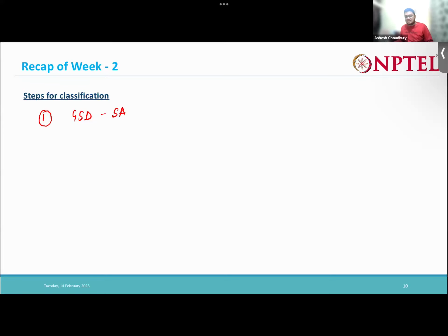It may be only dry sieve analysis, it may be wet sieve analysis, both, or it may be dry sieve, wet sieve, along with the hydrometer analysis. So you have to plot the complete grain size distribution graph starting from 80 mm to below 75 microns, whatever is possible. You need to conduct your sieve analysis along with the hydrometer analysis and plot your grain size distribution curve.